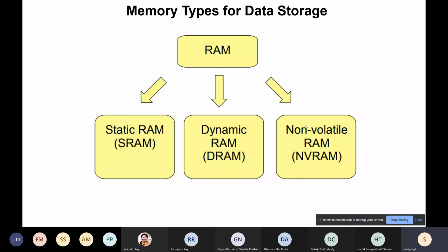So if you have fewer connections, fewer transistors, obviously less capacitance. As a result, your speed improves, because with smaller capacitance the time constant becomes low. So DRAM offers quite fast operation, but it depends under certain conditions. If you compare with SRAM in speed, but in space, DRAM really wins.